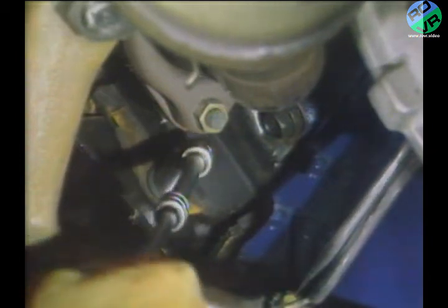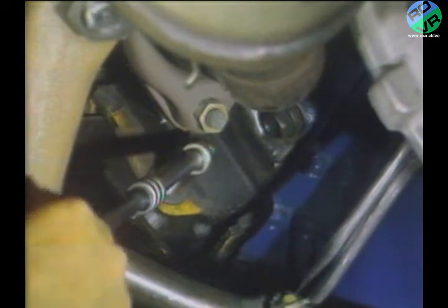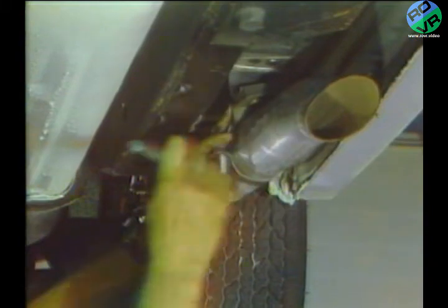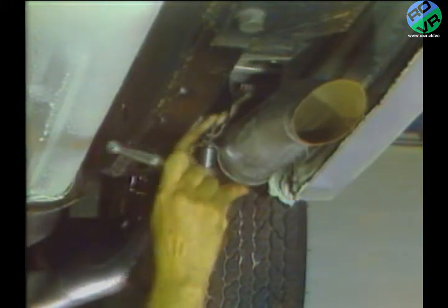Often, an abnormal vibration will be caused by a loose or mispositioned engine mount. Follow the procedure in the Vehicle Vibration Diagnosis Guide for neutralizing loose engine mounts. Grounded or abnormally strained exhaust system components can also cause noise and vibration problems. Reposition all exhaust system components and hangers as necessary to eliminate this type of owner complaint. Always neutralize the system when it's hot.